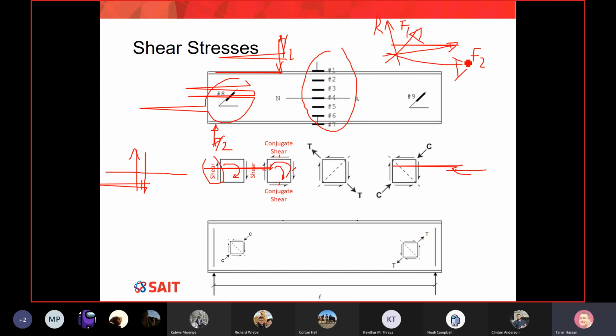And F1 and F2, if the two forces are equal, where is my R? If F1, F2 are equal, where is my R? The resulting force simply bisects the angle, huh? If the two forces are equal, then the R will bisect the angle in between. Our angle here is 90 degrees, and that's why the resulting force here is R, and this R will simply bisect the 90, which means at 45 degrees, okay?